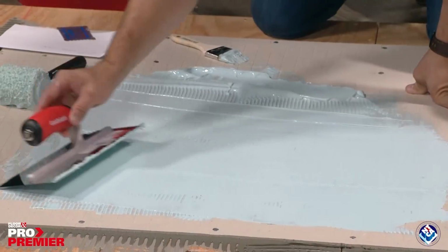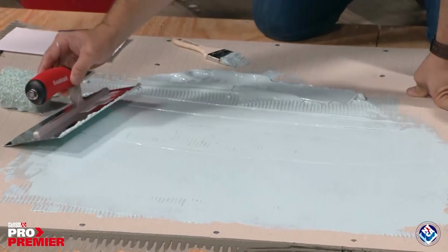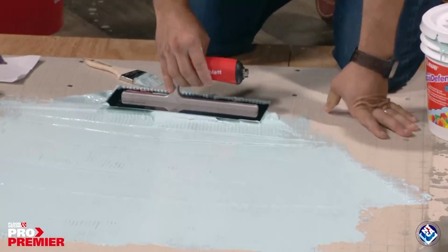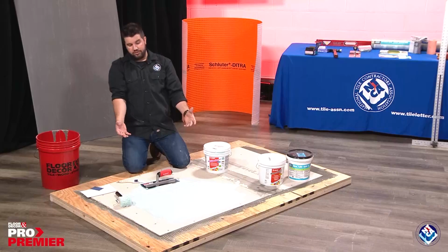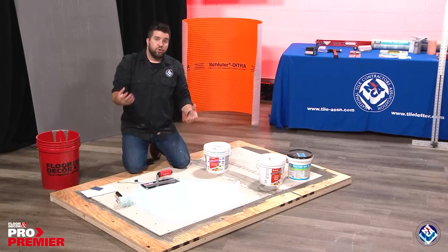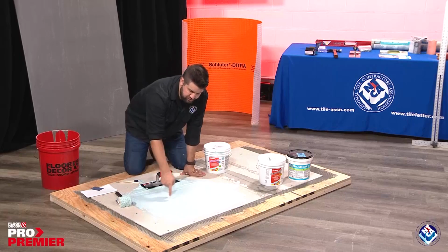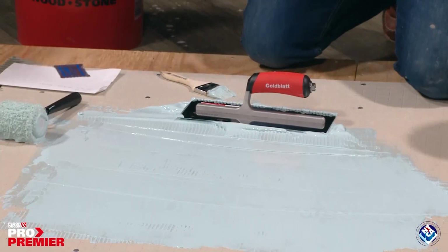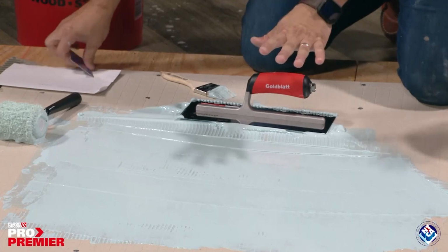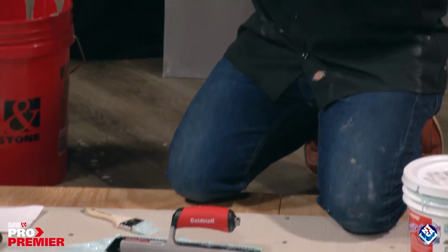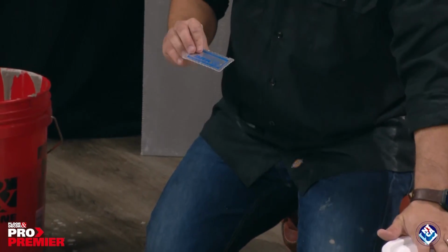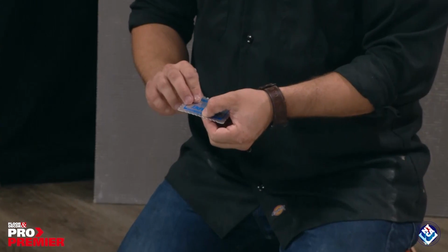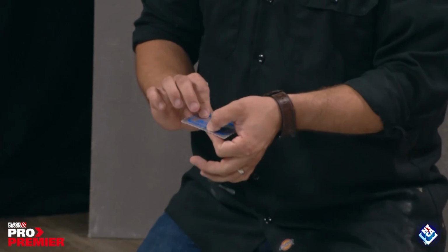So as you can see, when I do this, I've now got a much more consistent area covered, but it requires more than one coat. And so you'll notice that I have a couple of bare spots, and that will fill in as we add more material. So let's take a look and see how I'm doing on our thickness. So again, I've read the instructions and we are looking for 20 mils as it is wet.